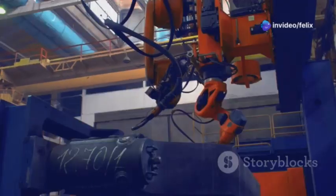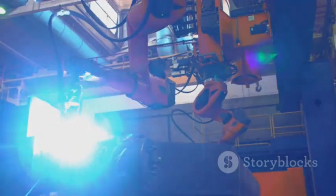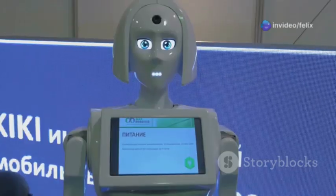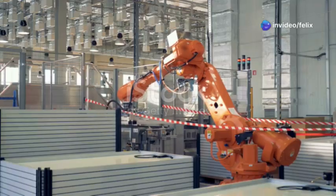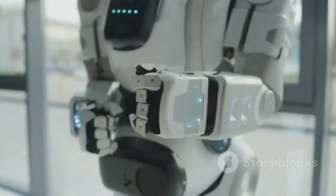Let's get started. First off, robot specs give us the nitty-gritty details about the robot's design, movement, and operating limits. The big ones to watch are payload capacity, degrees of freedom, work envelope, accuracy and repeatability, speed, power source, and control system. Alright, let's break these down one by one, starting with payload capacity. That's the max weight a robot can lift and move around. It's usually in kilograms or pounds.